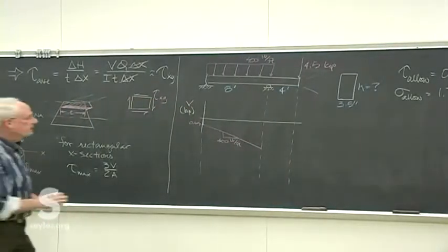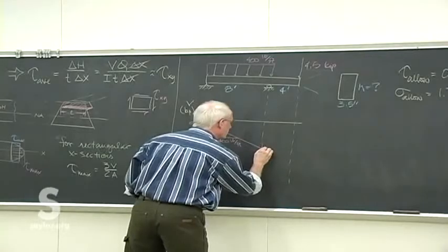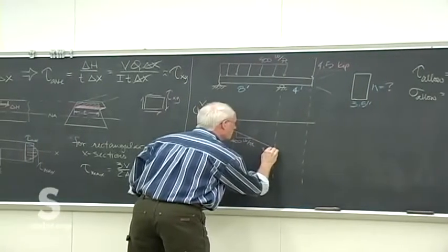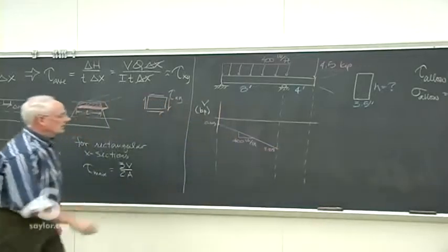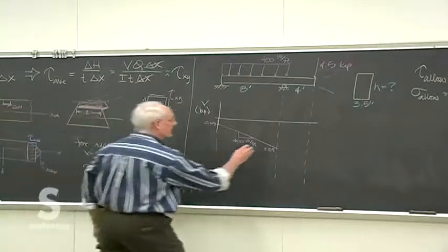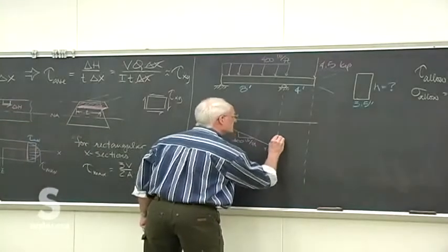Takes us down to a point of 0.385 kip. So, as we might expect, there's a worry about shear failure there. And then the reaction at the roller is 8.35, so it jumps up by that much.